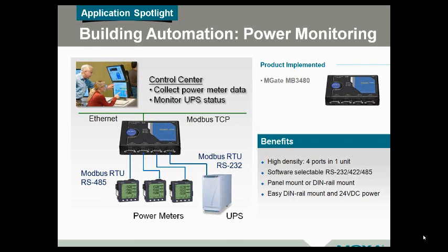One application, and I think you saw that power meter on here, we find there's a lot happening nowadays with folks looking at doing energy efficiency. And to be more efficient with your energy usage, you have to know where you're utilizing that power. And a lot of systems within building automation, this even overlaps with plant floor applications where you've got your power coming into a facility and have your switch gear. It's gotten quite commonplace to instrument that with a 3-phase power meter installed within those panels.